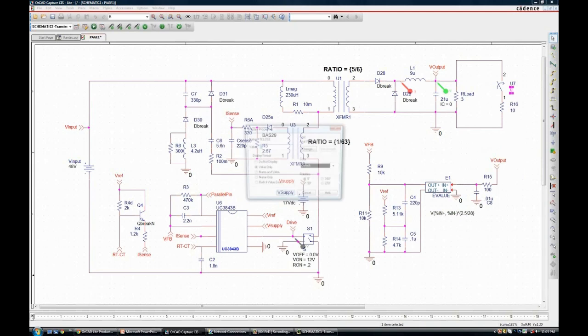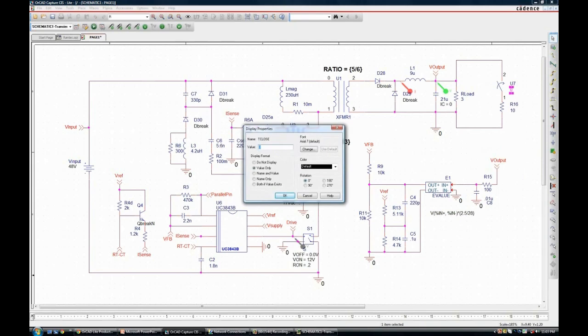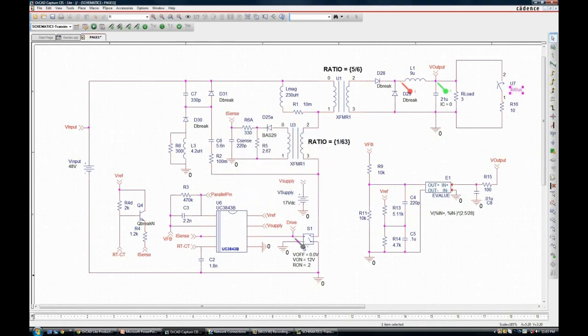And this is the time to closure. I'll set that to 400 microseconds. U is micro in PSpice speak, so that's an important thing to notice. And so now we have a load. It's running at 3 and will be running stable that way for 400 microseconds, at which time we will parallel in 10 ohms and the load will go up. I'll run PSpice with that in place.